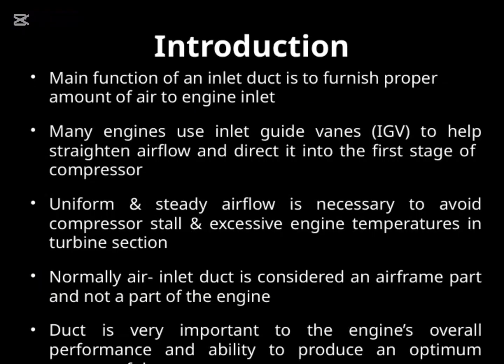The main function of an inlet duct is to supply the engine with the right amount of air needed for optimal performance. Many engines use inlet guide vanes, or IGVs, which play a crucial role in straightening the airflow and directing it smoothly into the first stage of the compressor. This is really important because uniform and steady airflow helps prevent compressor stall and keeps engine temperatures in check, especially